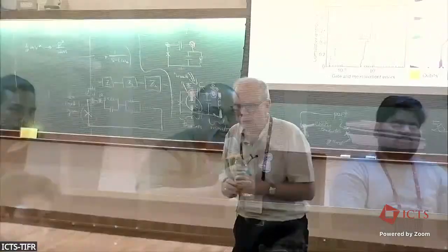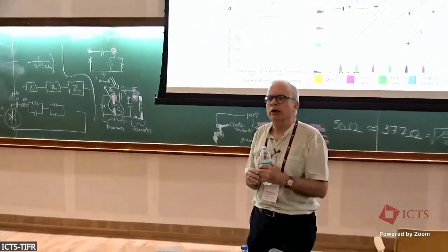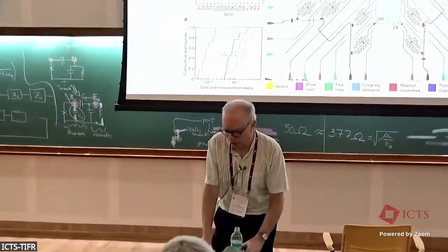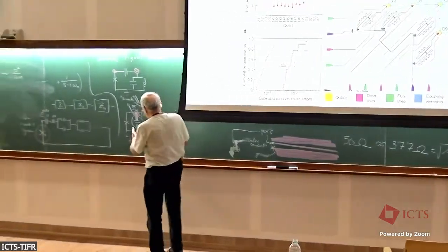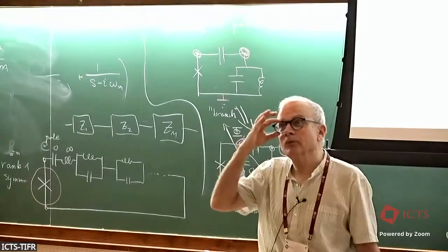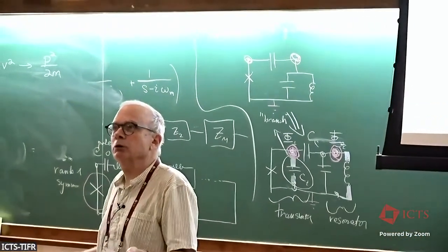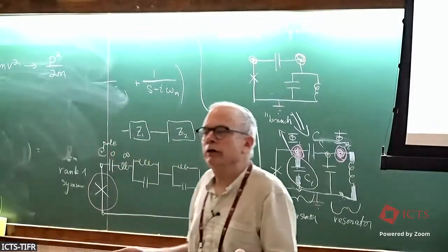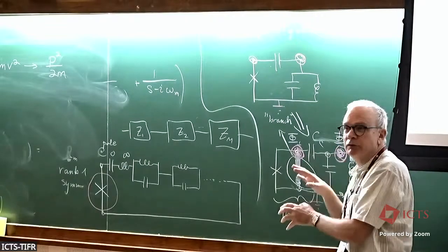Yeah, we found that it's sufficient to kind of impose constraints by hand, and I sort of did that here. That is, I started with a circuit with multiple branches. I have 1, 2, 3, 4, 5 branches. And so according to the way I initially said it, I would have had 5 variables, but surely that's wrong. And I've explained, so Kirchhoff's laws say that there are linear constraints among these branch variables.